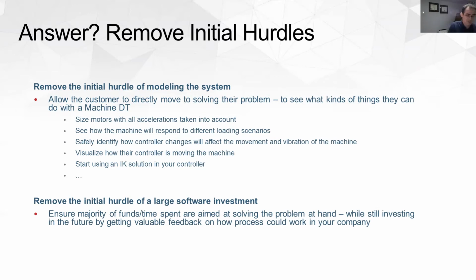So you can start sizing motors, making sure that you're taking into account all the accelerations and not just doing maybe a static analysis from an Excel sheet. Or you've got a vibration issue you want to investigate. See if that can be modeled inside the software, so in a safe way you can start modifying your controller right away to see how it can interact, and see if you can make progress on that control problem.